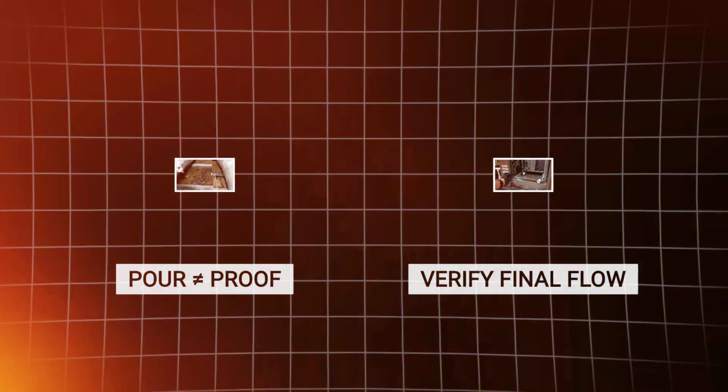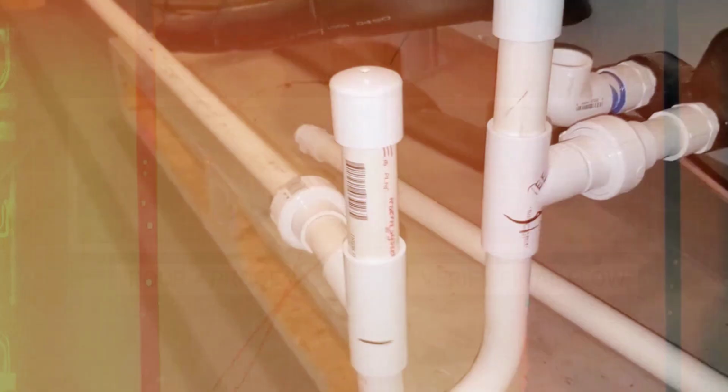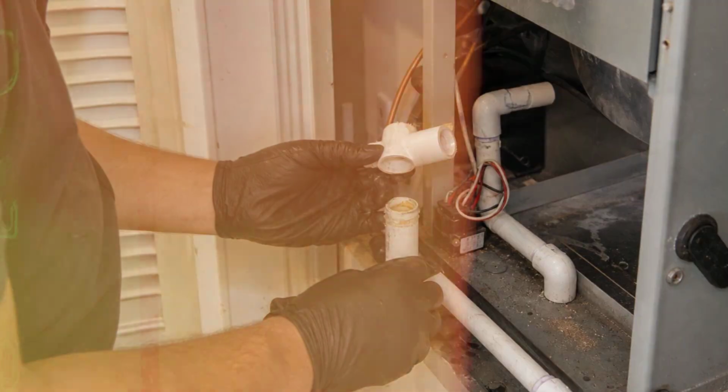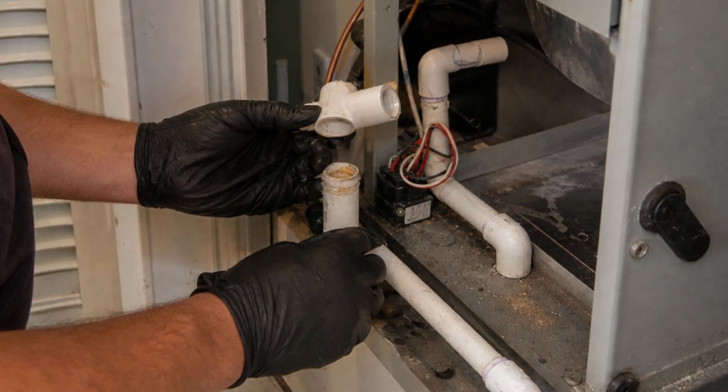If that route disappears behind finished walls, the outlet cannot be identified, the pan still holds water, or the float remains raised, the job is incomplete. A repeat backup also needs diagnosis because vinegar cannot correct bad slope, a disconnected fitting, or another defect in the drain assembly.